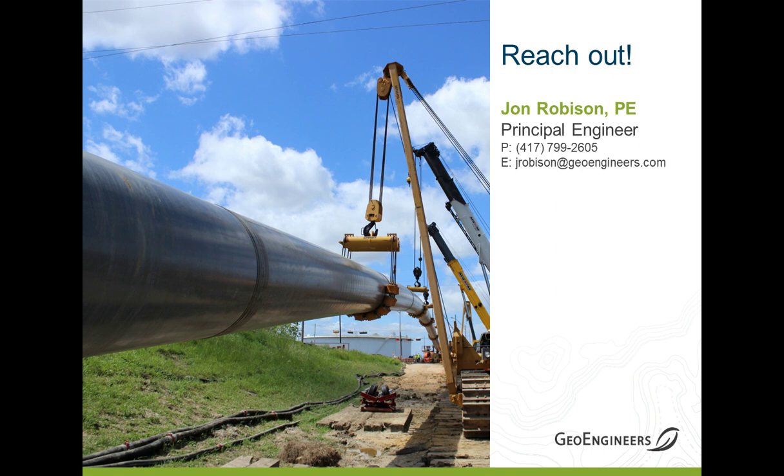I think it depends on what you're under, and it depends on the geology that you're in, and what your concerns are. But it would be comparable, I think, to a microtunnel, maybe 2 or 3 times the diameter. We typically want to be a little deeper than that, just for general comfort level. But again, it depends on how critical the thing is that you're under, and what the geotechnical risks are. But 2 to 3D would be maybe a bare minimum starting point.